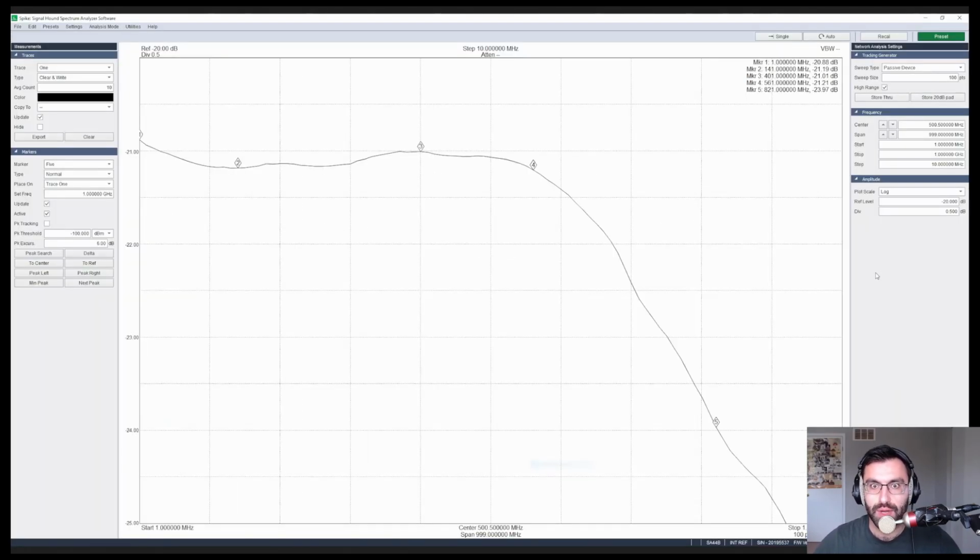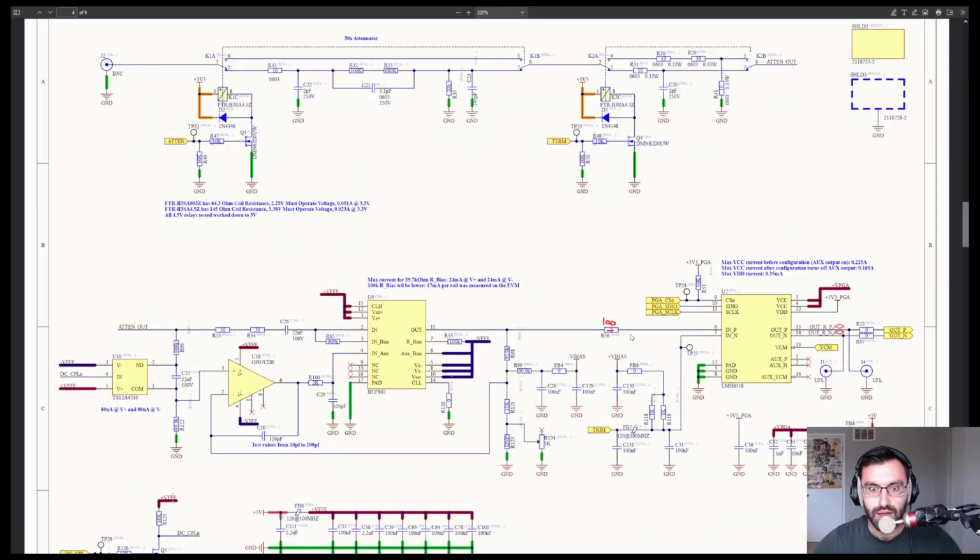So we got to thinking about the circumstances behind this measurement, and I realized that this is coming straight out of the buffer. So this isn't actually out of the PGA. So how did I connect the buffer? Well, I connected the buffer with a series resistance of 50 ohms to match the line and into the scalar network analyzer.